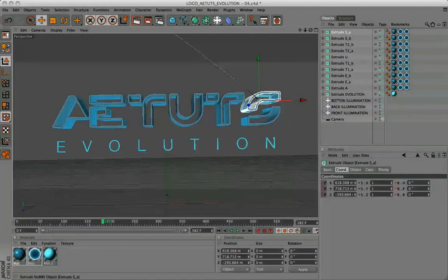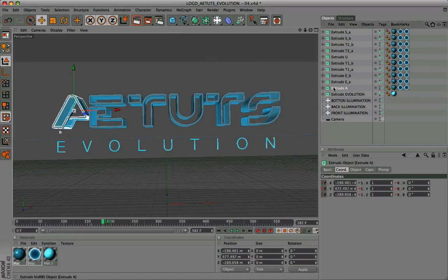To complete this animation sequence, we have to recreate the neon effect that shuts down intermittently. To make this interesting effect, we make sure that the letters are disabled, starting from the outside inwards. In our case, starting from a letter up to the U letter. To simplify this operation, we can directly implement in Cinema 4D the Display Tag tool.